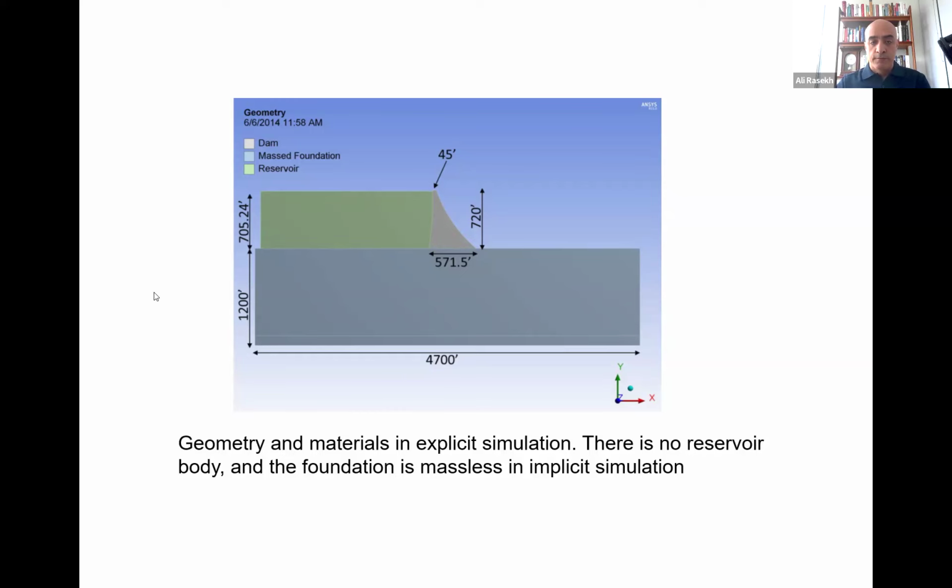Like there are these two terms, verification and validation. And a lot of times you mistakenly use one for the other, but both are about trust in the outcome and in the results. And formally, if you want to be really correct by the book, you should use verification for numerical modeling verification and validation for comparison with test, but that's not what people like. Sometimes they don't do that. So listen to them carefully.